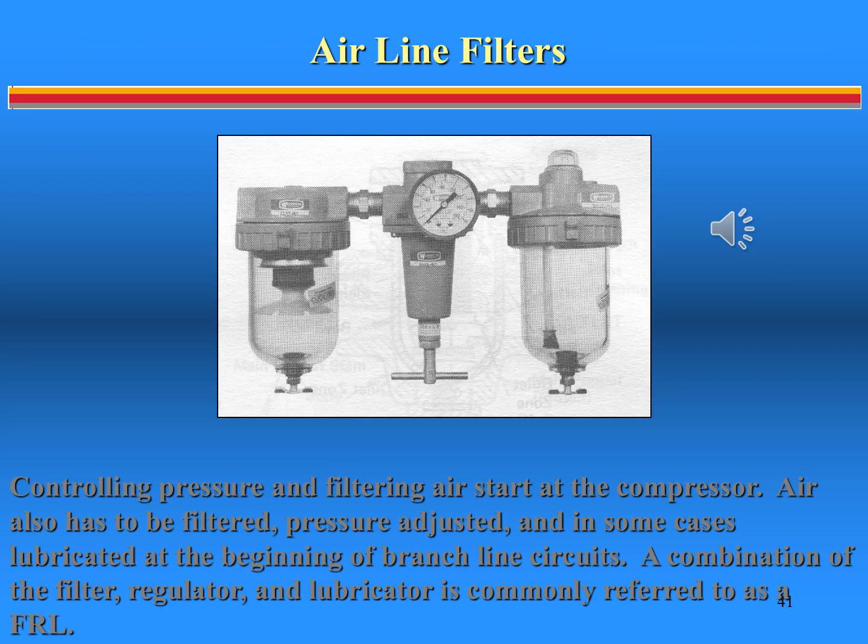Airline filters, such as the one shown in this slide, are the last line of defense in a pneumatic system against contamination and moisture. While they are designed for trapping these contaminants, the presence of these at this point is a warning sign that there are problems upstream toward the compressor.